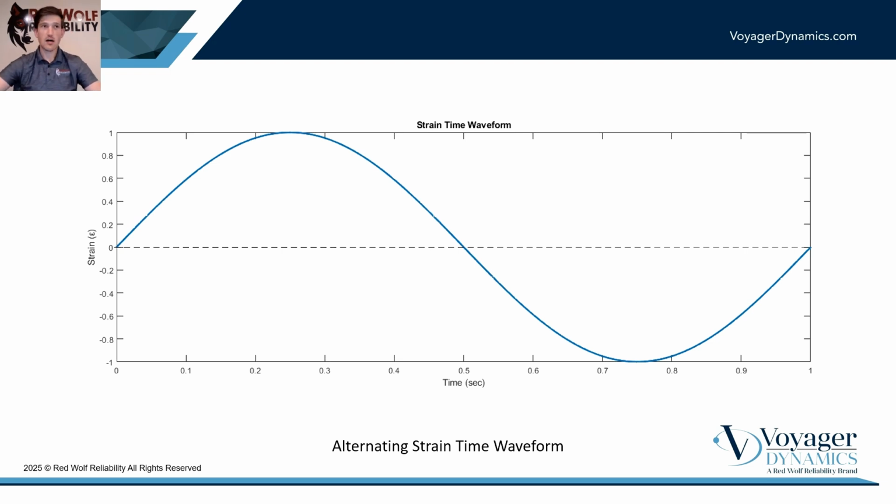Because the FDS sensor is a vibration sensor, the FDS sensor can provide you with a time waveform and any other vibration plots you would ever need to diagnose problems. In this example image of a time waveform, we have a maximum strain of 1 strain and then a minimum of -1 strain. You can see that that's occurring at a fixed frequency where it increases over time till it gets to a point and it smoothly decreases in a sinusoidal fashion.